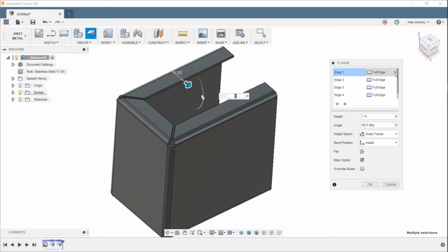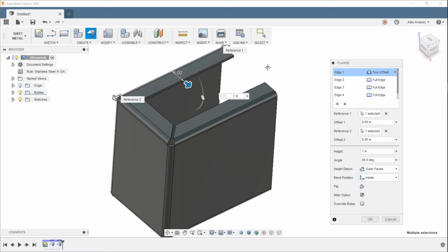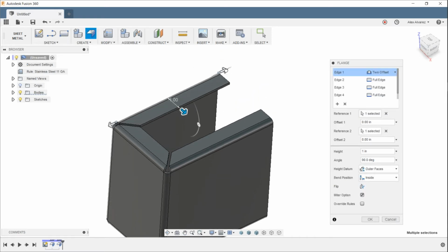And what you want to do then is hit the little drop down, and you have a few options here, right? So do you want that edge to be symmetric? In this case, we don't, right? Because otherwise, if we pull this back, it's going to pull back from the front as well. Instead, what I do want is a 2 offset, right? So I don't want an offset here, but I do want some sort of an offset from the back, right?